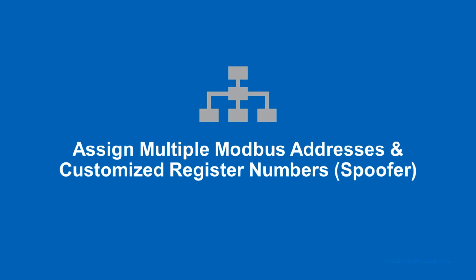All right, so let's talk about our third option, which is the spoofer mode. And this is a new one for Precision Digital, so this might be the first time you've seen this. Let's walk through what we're actually saying here. Assign multiple Modbus addresses. And by that what I mean is the individual IDs assigned to the products. Sometimes people call those the Modbus address,